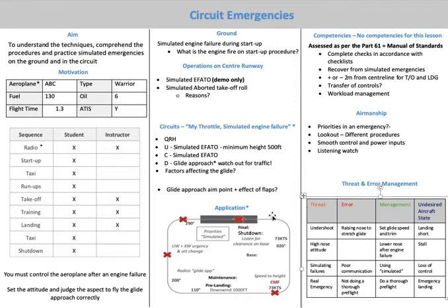And in terms of the glide approach, aim point, and the factors affecting glide, we've got temperature as well. So if it's hot and high, you won't glide as far. We've got less dense air, the prop is biting less air, and there's less air flowing under the wings. Things like air density, pressure systems. Also, another big factor is wind. So if you've got a strong headwind, it will decrease your range versus a tailwind, which will help you reach the runway.